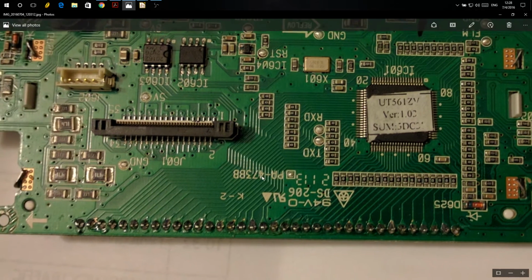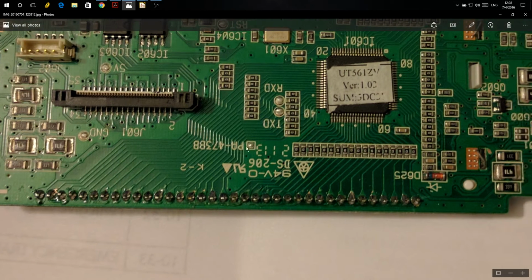Now the LCD in here is a passive display. If you don't know anything much about passive displays, things like calculators and things like that use passive displays. They're not active displays. They don't have transistors in them. It's pretty much you have to use a square wave or the like to drive the segments.